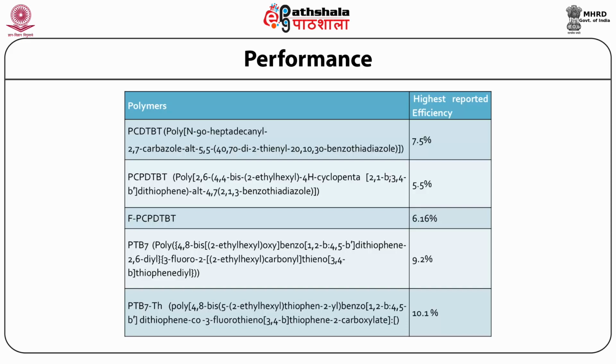Due to much higher light absorption and improved exciton dissociation efficiencies, the active layer of OPV devices is the blend of two organic semiconductors, typically using poly-3-hexylthiophene, P3HT, for the hole transporting material, an organic semiconductor, and 6,6-phenyl C61 butyric acid methyl ester, PCBM, a soluble fullerene as the electron transporting material.